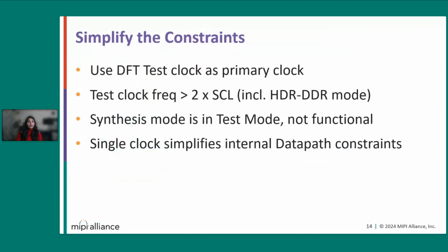Since I'm talking about this synthesis optimization, we know that the functional constraints are of course necessary to qualify the functional timing during the timing analysis and functional sign-off. We propose to simplify the constraints during synthesis by first defining the test clock as the primary clock.